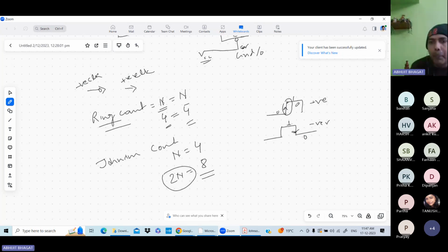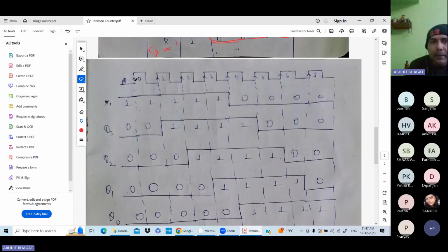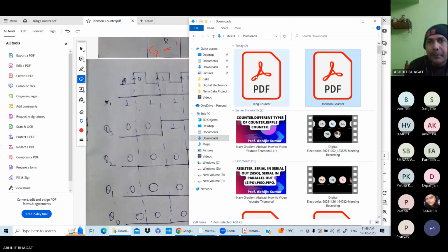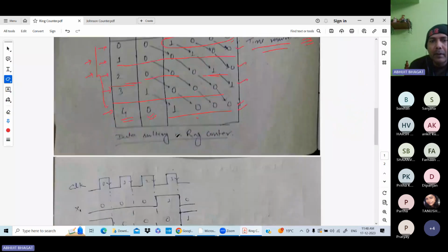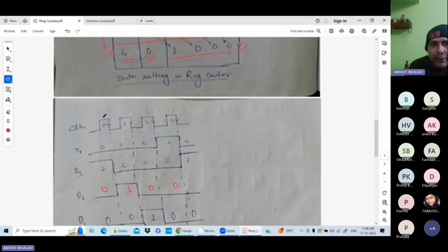Compare both previous diagrams. For the positive clock pulse, the 0 to 1 transition is the edge for the positive clock. For the negative clock pulse, the 1 to 0 transition is the edge, and the count value will change at this time.